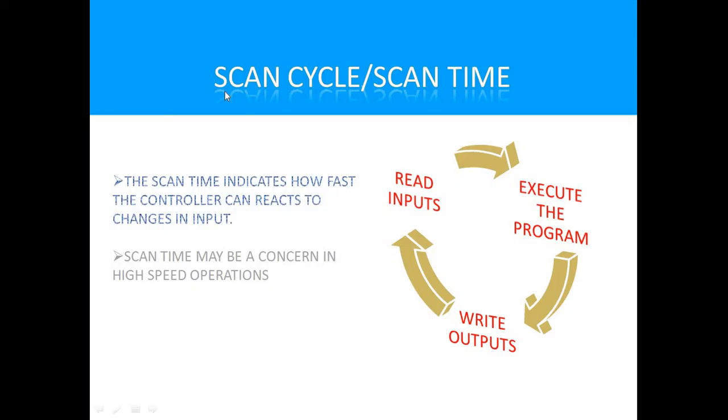So scan cycle or scan time. It is the time required to read the inputs, execute the program and write the outputs. It indicates how fast the controller can react to the changes in input. Scan time is a major concern in high speed operations.